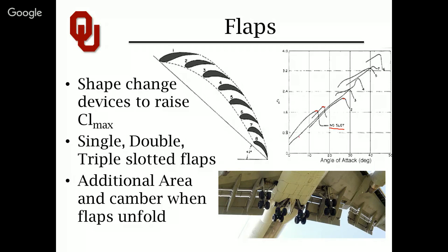But see, it's also continuing the lift curve slope to higher and higher angles of attack. So now the CL max, which is approximately what, 2.1 in this case, occurs at 28 degrees. And so 3 slots, 4 slots, 5 slots, 6 slots, but then 7 goes back down. So in this study, with these particular circumstances, in this particular test case, 6 seemed to be the magic number. I wouldn't take that all the time, but for this scenario, it happens to be that case.